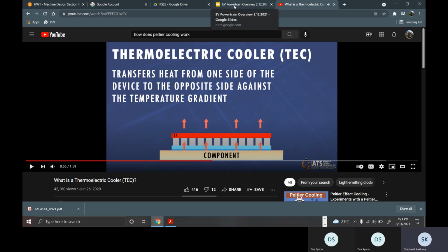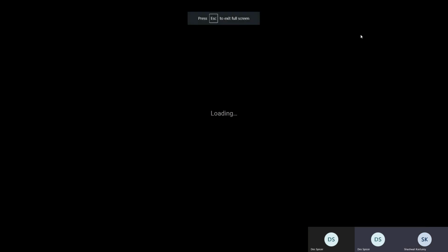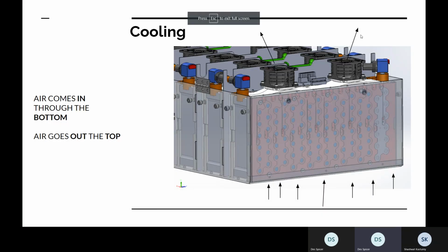So, no. Using the battery pack to power Peltier coolers to cool the battery pack is backwards and inefficient. Those things are like 30% efficient at the most, and you're paying like $500-600 for a Peltier that can pull 30% efficiency. The thing is, if you're passing air fast enough in high enough volumes, it doesn't cool appreciably. You have to have a certain amount of interface area for a certain amount of time for heat transfer to cool effectively. So not really feasible for our application.